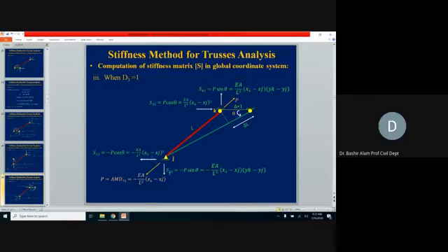Similarly here, if you see, the displacement given at 3 was in the horizontal direction, but the action produced is in the vertical direction. So horizontal and vertical both are involved. Similarly here you can see P, it's a tensile force now. So here it was P and this is also P now, EA over L square and xk minus xj.